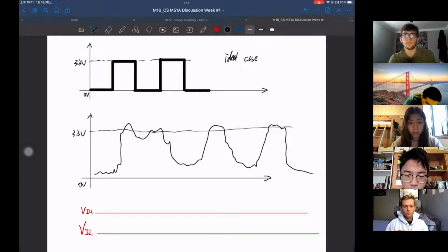In that case, for example in a CMOS circuit, we have 0 volts standing for the 0 bit, and 3.3 volts, which we decide is the 1 bit: 0, 1, 0, 1, 0, 1. This is a square wave, simple and plain enough, right? However, in real life, the real world doesn't work in this way.